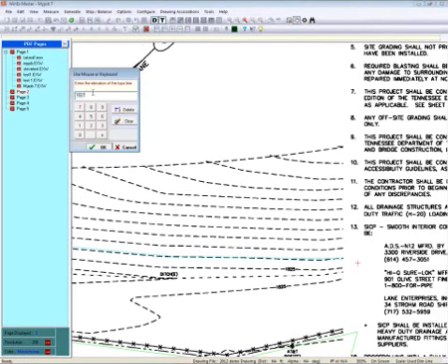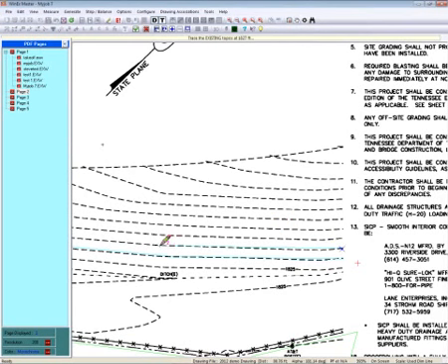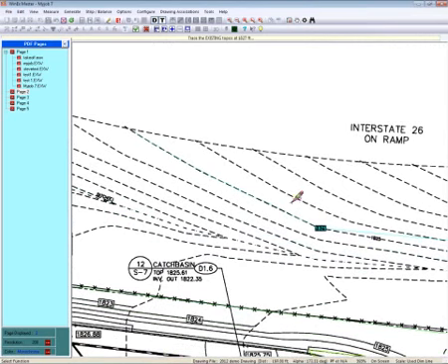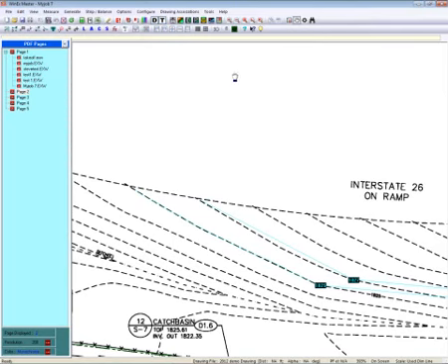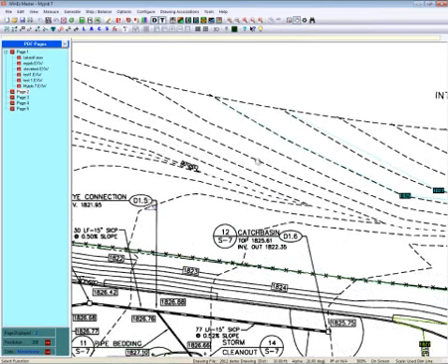Let's say this one's at 1827. Click OK, and then, again, where the straight area is, just click along, and I'm going to come up here, and then when you're finished, just click Finish. Now, I'm not being very careful with this, but if you needed to do another one, when you put in the third one, it would take the interval between these two and automatically set it at 2 feet. So the rest of them you wouldn't even have to put in the elevation. So that's how easy it is to do topos.